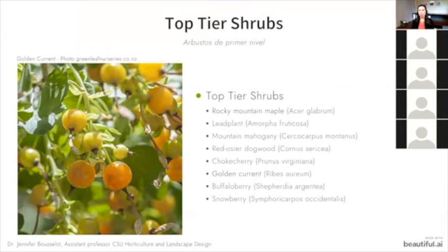What we're talking about now is really more of the HOA level, or the small commercial level, or the residential level. Rain gardens, when I talk about top tier, mid tier, and low tier. When we have rain gardens that are for water quality, as part of your MS4 permit, you want to have a very flat bottom so that sediment can distribute properly.